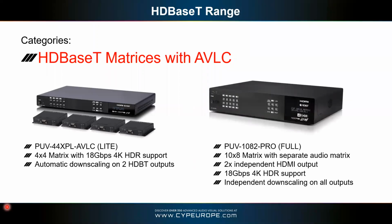You've then got a full 10 input, 8 output matrix, our sort of flagship there, which again has the AVLC technology. This has all the features Kev's just described as well, with the audio matrix, the independent HDMI outputs, but again, this one then supports the 4K HDR, thanks to our AVLC technology, and it has independent downscaling on every single HDBaseT output. So again, if you need to combine 4K screens and 1080p screens in a system, no need for separate downscalers.